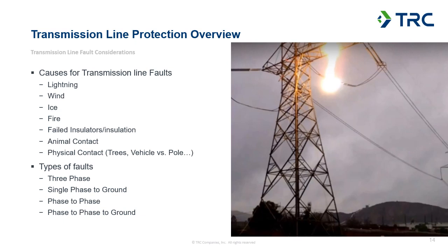We put down crushed rock to prevent vegetation from growing. We may put provisions in to avoid animal intrusion of the equipment to prevent faults from that.